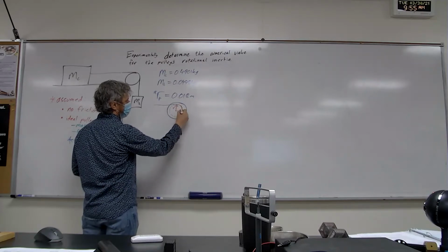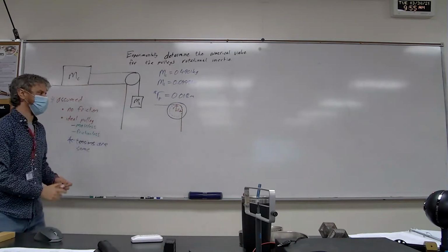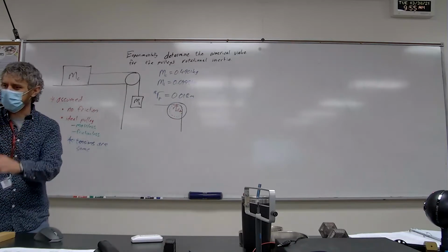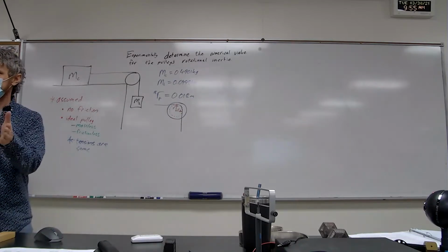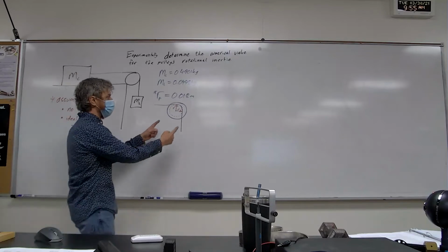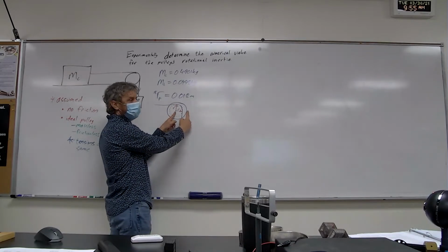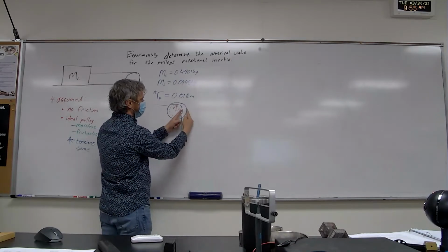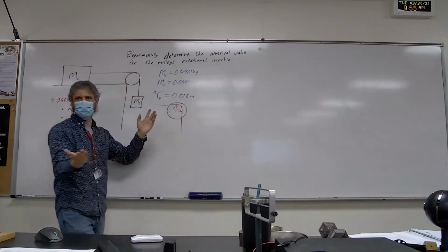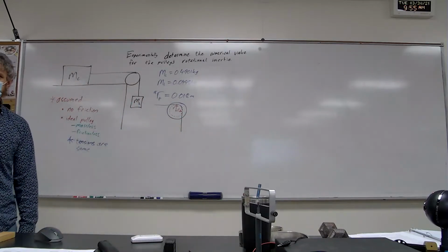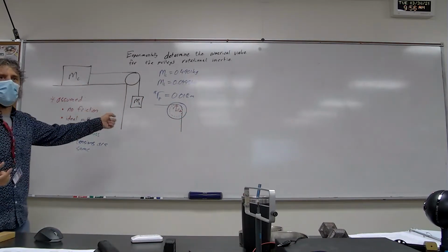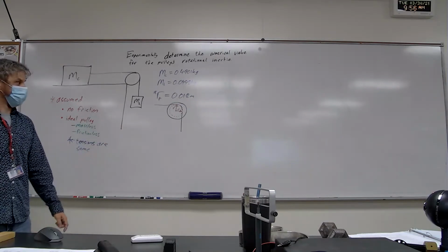Okay. So the lever arms for those forces aren't going to be the radius of the pulley as you see it here. It's going to be that distance itself. And to measure that, all I did was measure the radius of the pulley. And then I took my ruler and I stuck it down in the groove, measured that distance, subtracted it. That's how I got the actual radii that will be the lever arms for the tension forces. Okay.